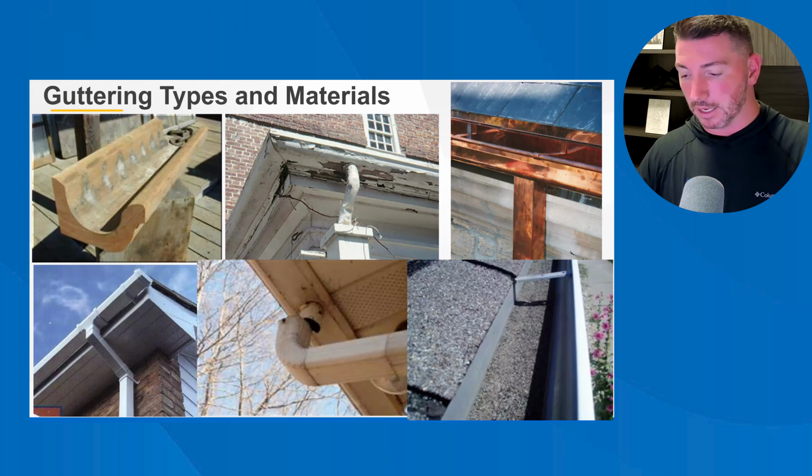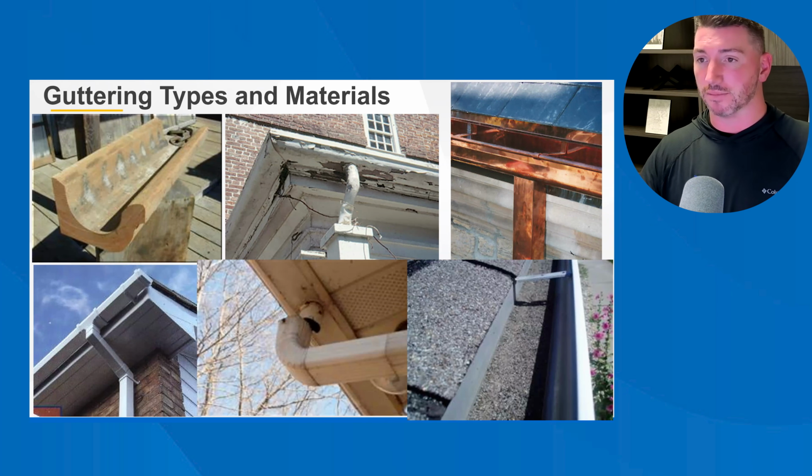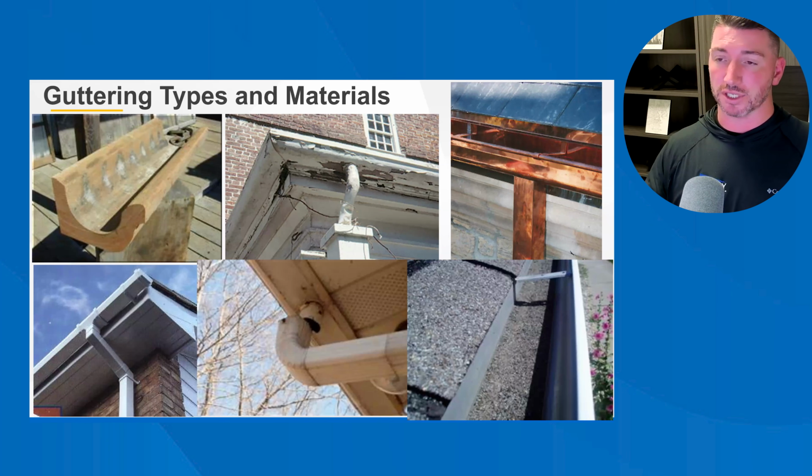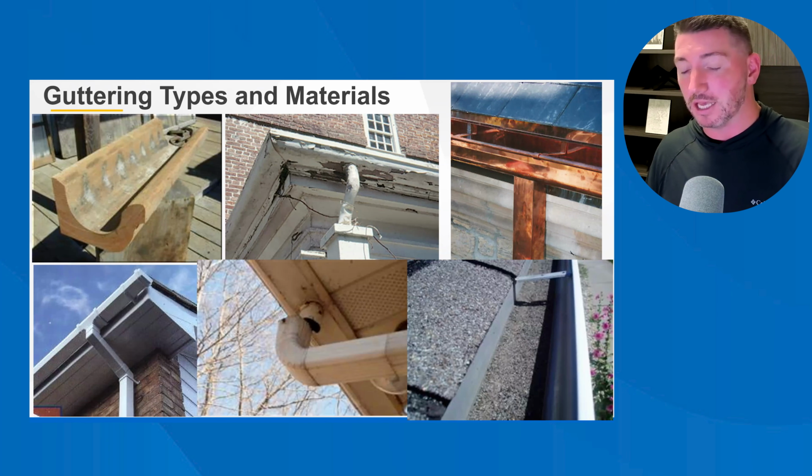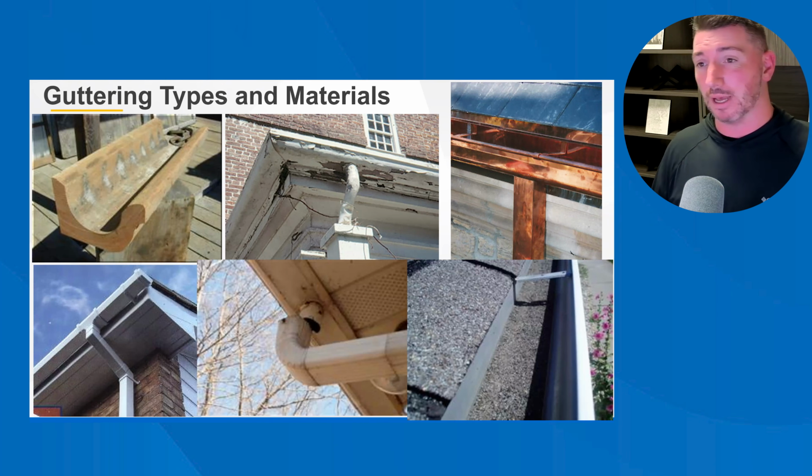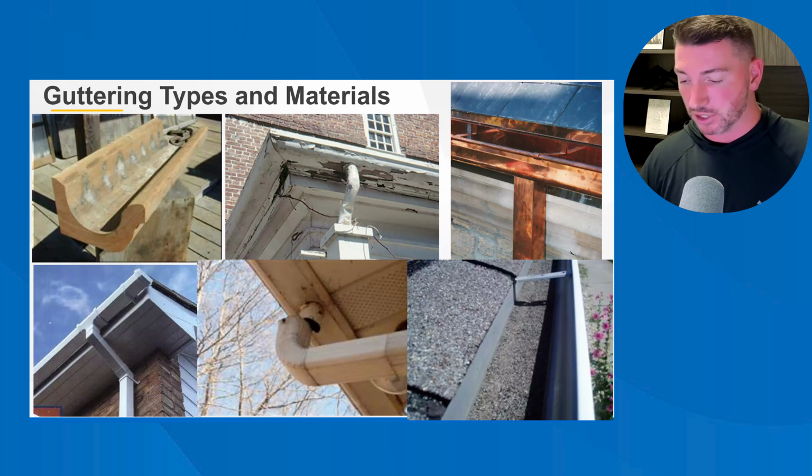It may appear on high-end new construction and on quality restorations of older properties. What makes copper systems desirable is that all the joints are soldered, including those of the downspouts. That tends to make for a system with a long service life. And that's true. The seams on those systems, they actually have to heat them up with a torch and solder them. Now, one thing that you may look for on a copper system is whether or not they overheated the copper and damaged it using that torch. Because, like I said, it may be a lost art, but usually those copper systems are going to last a long time. The price reflects that.